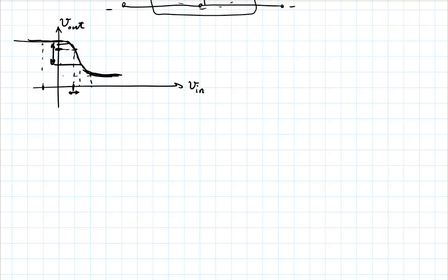The point that you're operating around is called the bias point. And the variation that you have around it is called the small signal. So consider, for instance, in your lab, you had this function generator, the waveform generator. You could have a sinusoidal signal with some amplitude, but you could also have an offset, right?